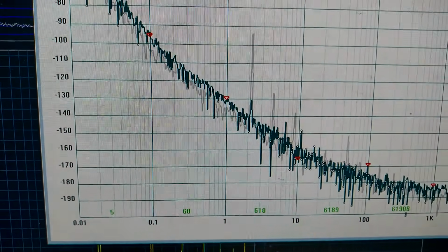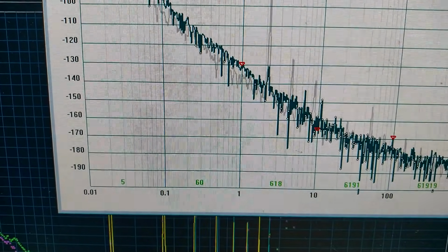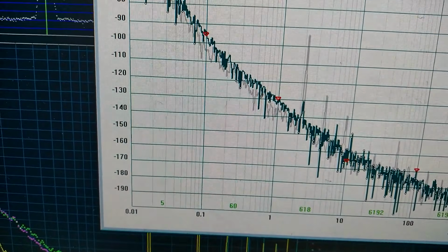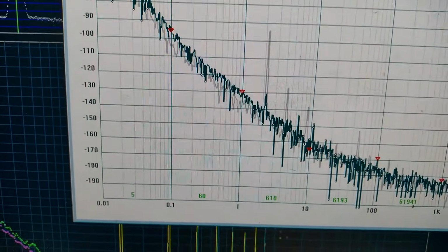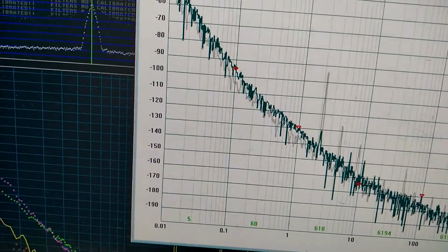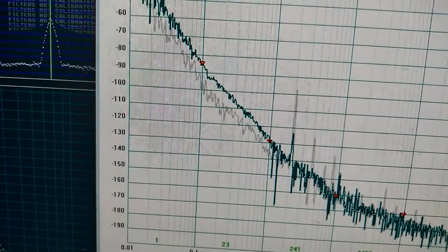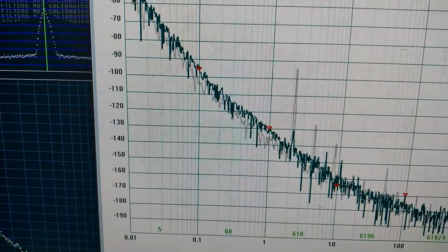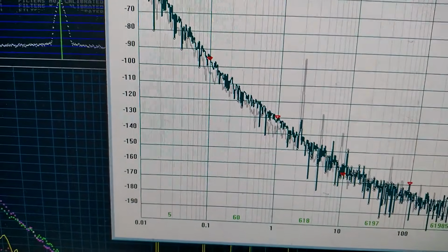The result is interesting. It seems like minus 131 at 1 Hertz and minus 95 at 0.1 Hertz. So this is quite good, but the box is still filled with cotton, although this time the cotton filling did not work very well. I have an image here. This is what it looked like. I showed it recently. This is the same. So this improvement comes from the 5 millimeter aluminium.